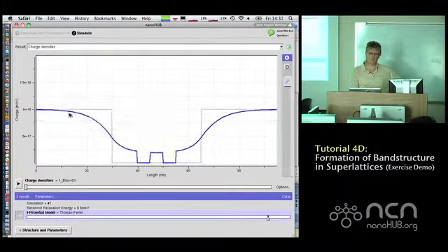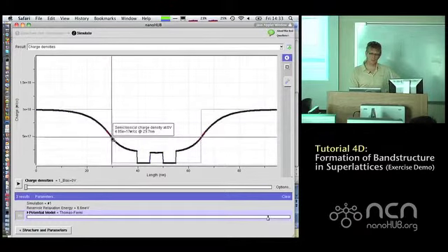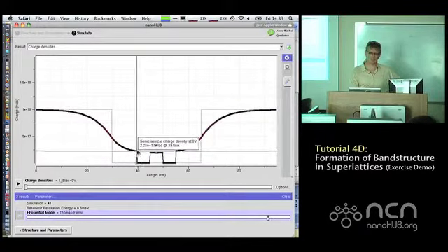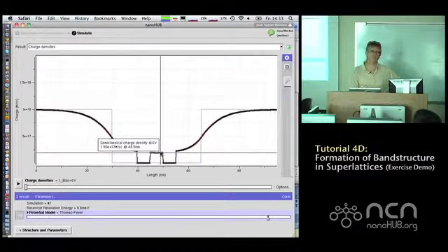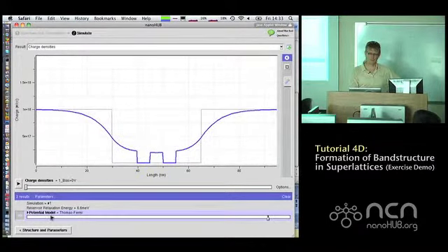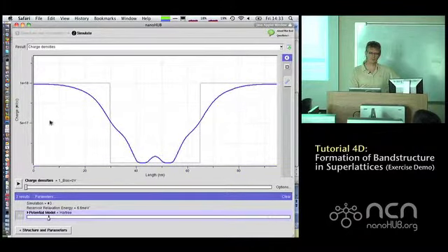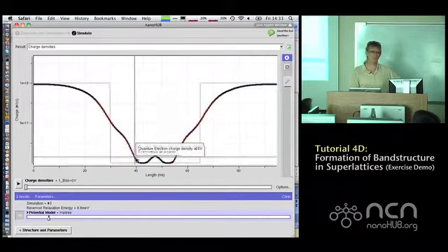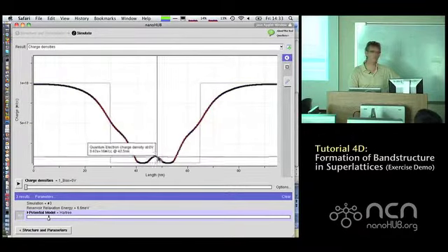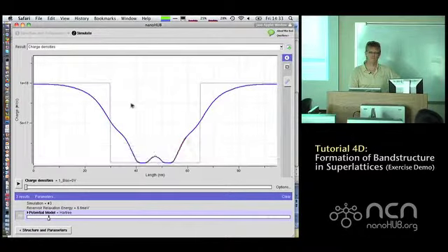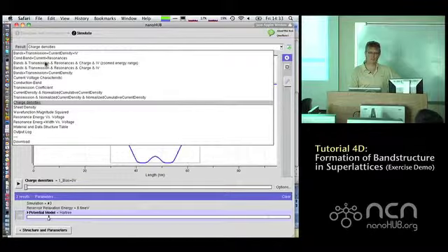In the semi-classical case, there's charge piling directly up to the barrier, then nothing, and then basically a square inside the well. In a quantum mechanical sense, it is not piling up hard against the barrier, but it's penetrating a little bit into the barrier and decaying, so it's smooth, and it is smooth on the inside. So now you can also look at the